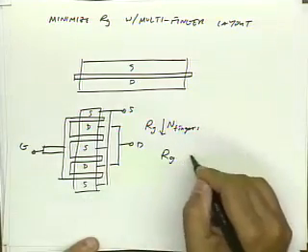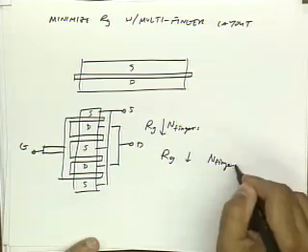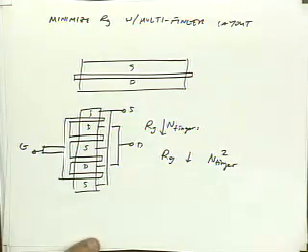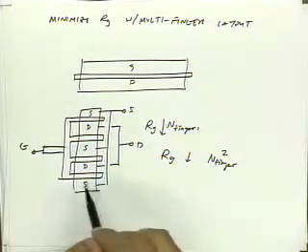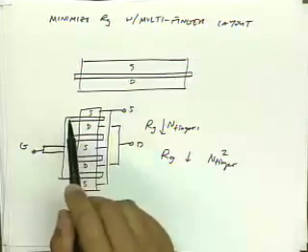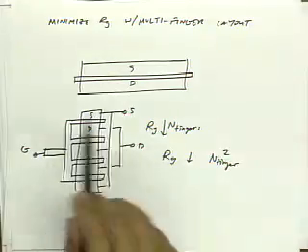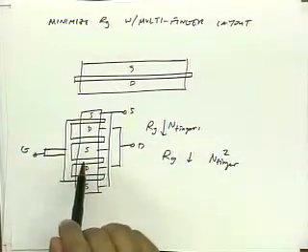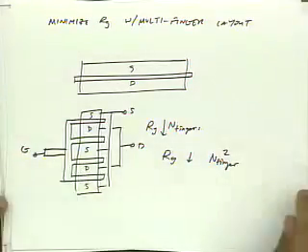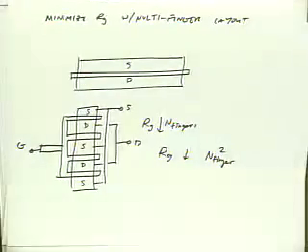So our gate resistance goes down like n fingers squared. So this layout is much superior to this layout. So first thing you do when you do high frequency layout is you go in and make all your transistors multi-finger devices to make them nice and low gate resistance. Okay. Questions?